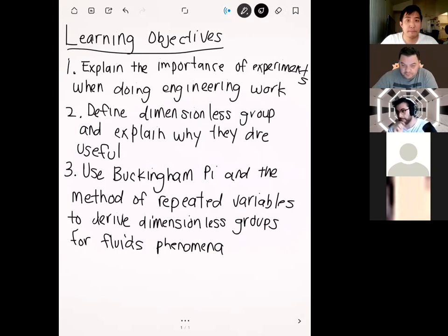Can you remind us what W equals U minus VCV is? W equals U minus VCV. That's your relative velocity, for a moving control volume problem. Basically, that's the velocity that you observe if you're sitting on the control volume. If your control volume is moving and you're sitting on top of it, the fluid velocity that you observe is not the absolute fluid velocity, but the difference between the fluid velocity and the control volume velocity. You can imagine your control frame or reference frame is moving. Thanks. Yep.